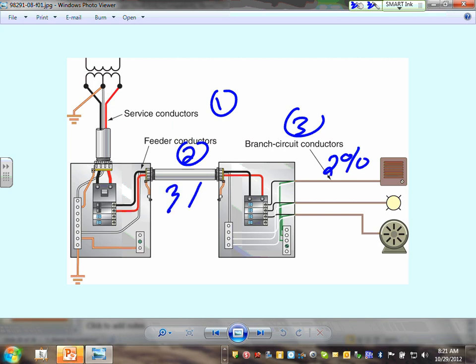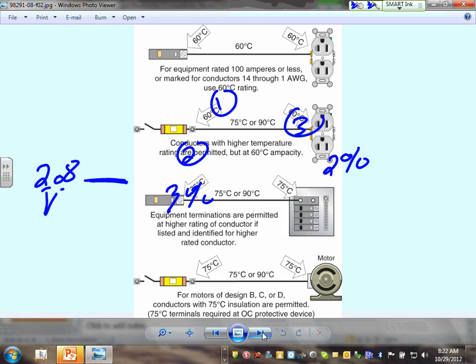Okay, so when we have a voltage drop, this will be your 2% here, this will be your 3% here, and you're always right at this point, you want 208. You want the utility to give you 208 right at this point, right? If you get less than 208, you have to call Xcel because your start point is screwed up. If your system is 480, what do you think this will be? Your start point has to be the actual voltage.